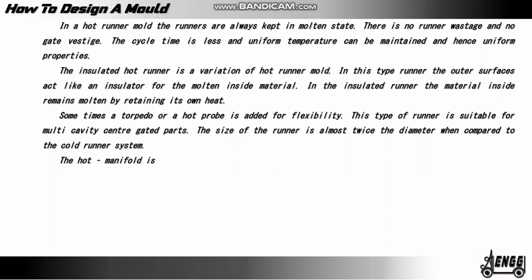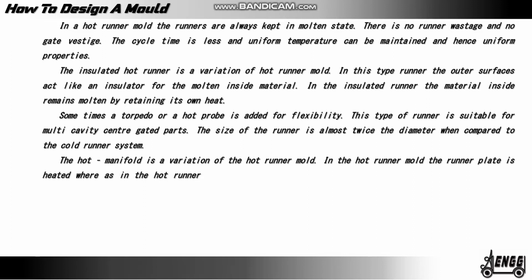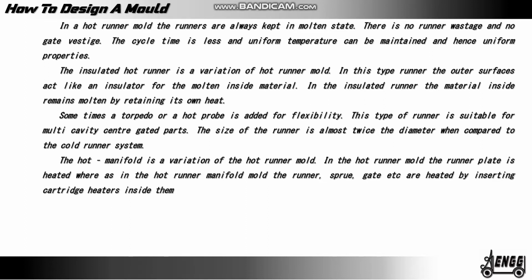The hot manifold is a variation of the hot runner mold. In the hot runner mold, the runner plate is heated, whereas in the hot runner manifold, the runner, sprue, gate, etc. are heated by inserting cartridge heaters inside them.